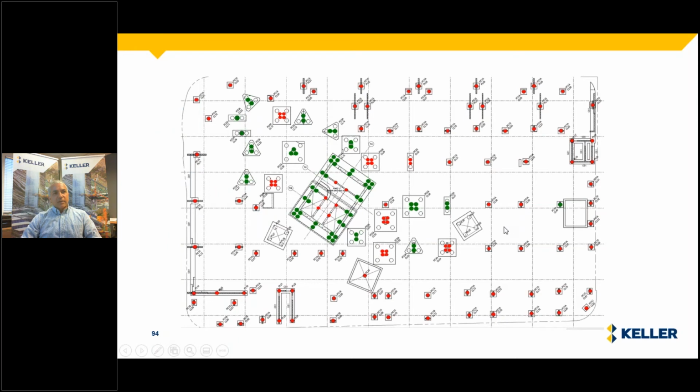Some of the layout on that project: some columns supporting one single element, some others multiple ones. They did have a distribution of larger caps that you see, and then there was a proposal to reduce that spacing to get a tighter formation and less punch and shear on the caps. Through a load test being performed, it was proven that the distance in between the installed piles was going to be sufficient, and will save time by not having to build a larger cap on top of them.